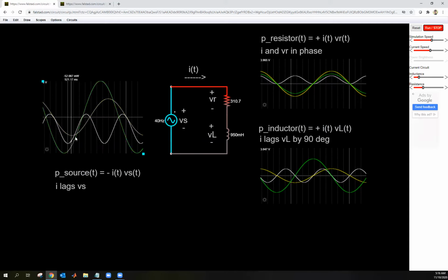And what this is saying, just like the plot before, is that in the average, this voltage source is delivering power, right? Because negative means this guy is delivering power. But there are points in time right here that it is absorbing power. That means this inductor is kicking energy back into this thing. It's bouncing it back, okay? And then let's just reason that out.